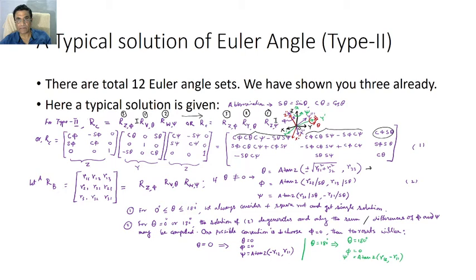So this is x1, x2, and then y1 and y prime 2 are the same because you are rotating about this axis, followed by a rotation about the rotated z axis. So looking from here, these are the three operations which have been given, and as a result you see this is a coordinate frame, and they are representing, say, a body.